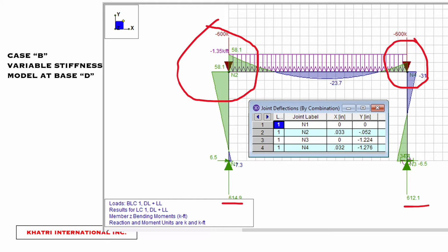And this is where the problem occurs, because when you have the redistribution of the stress, the new loads are higher than what was there before, and now that deflection in that column is now affecting the rest of the building, which will lead to instability. And we are getting horizontal deflections, as you can see. Look at the X dimension there. We're getting horizontal drift that's occurring in the frame. So the frame is drifting to the right, which will lead to a P delta effect. Now in this case, it may be okay with only 1.25 inch deflection, but it can easily get out of hand. You'll see in the next slide.